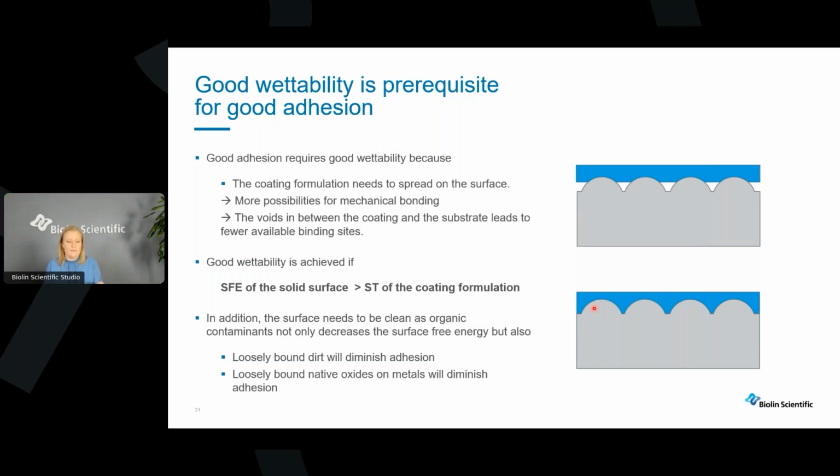This gives more possibilities for mechanical bonding. But also, this is a super simplified picture, if the wettability is not good, there will be voids between the coating and the substrate, which will lead to fewer available binding sites.